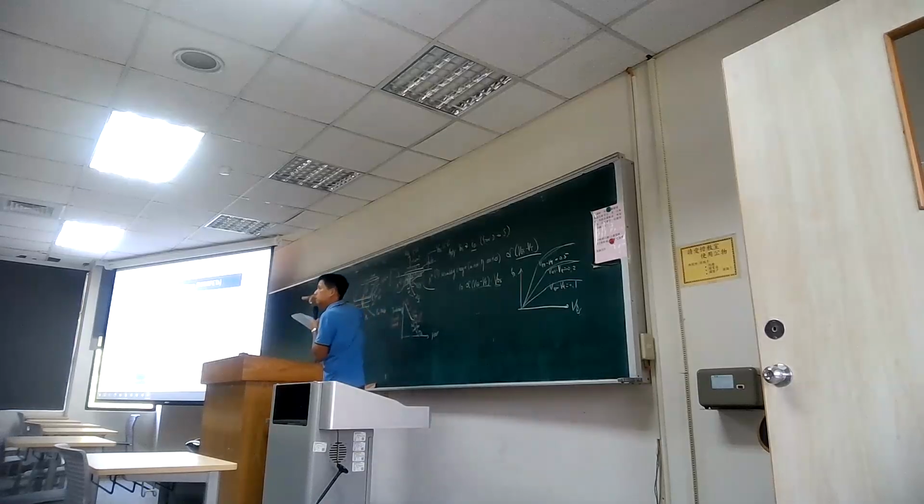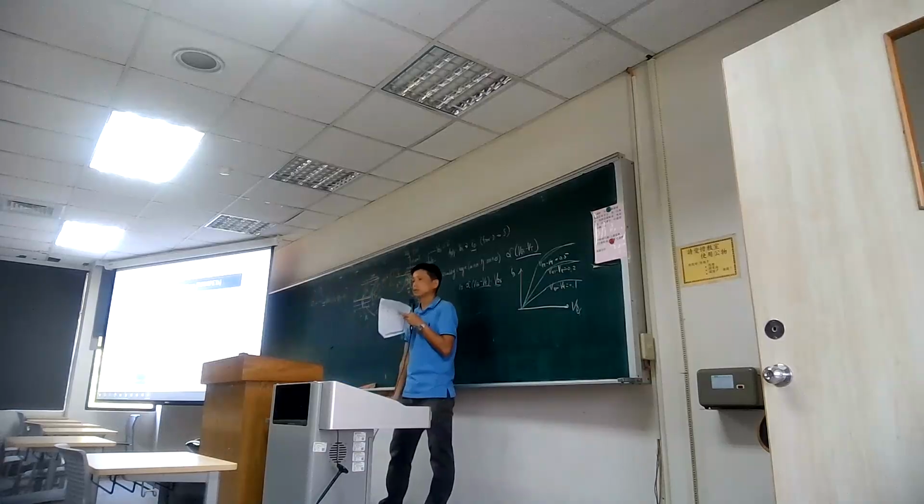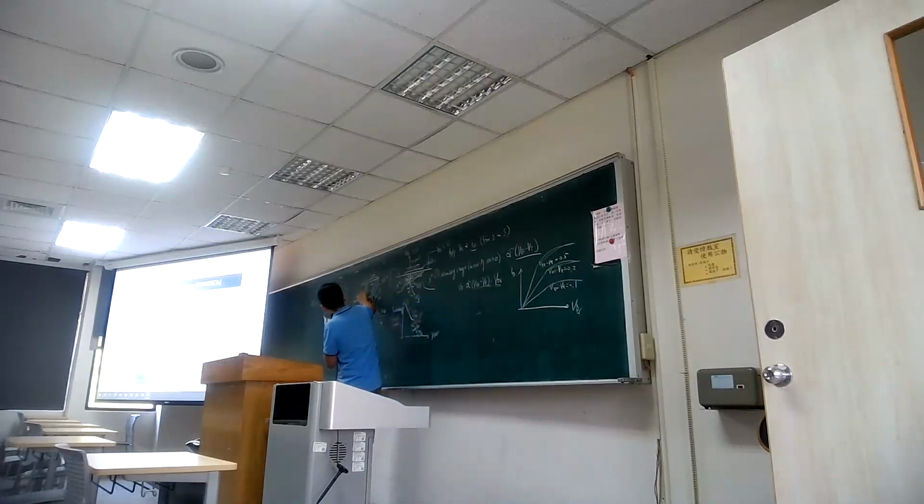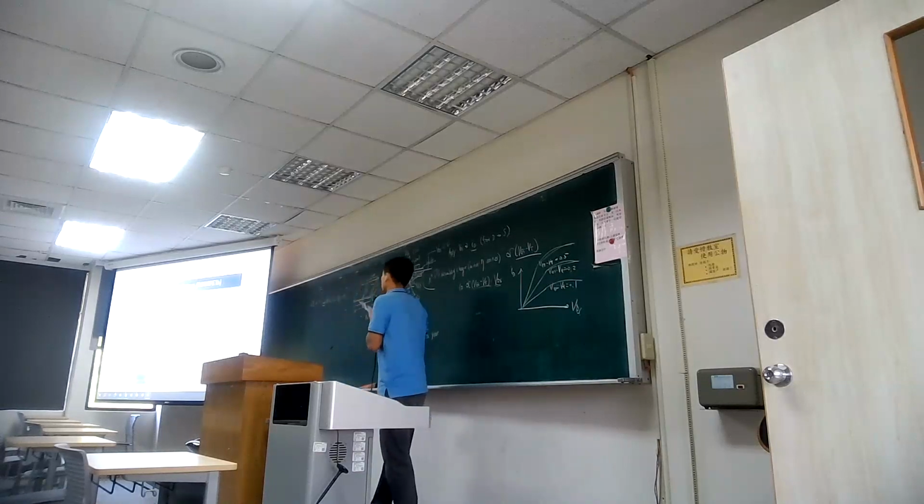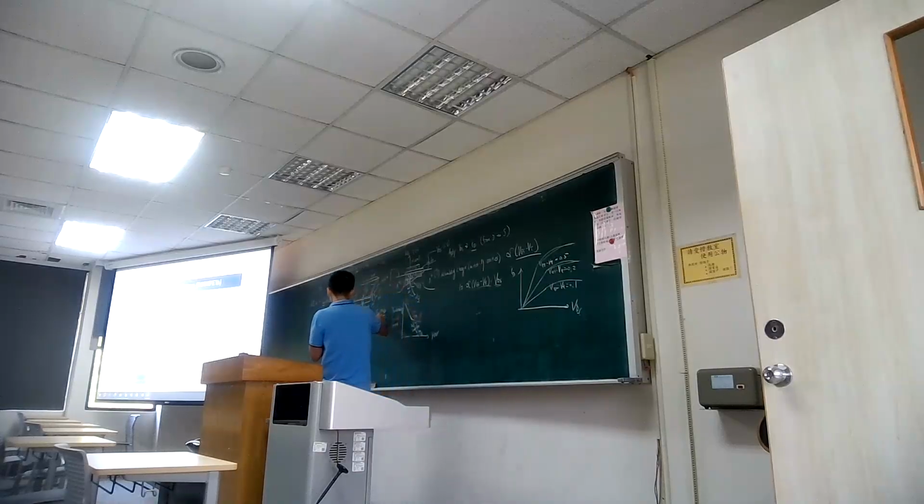And what is the distance between the two plates of the capacitance? It is T oxide. So you can write this area or the unit capacitance this way. What is the area of the charge separation? And what is the distance between these two charge separations? We get epsilon oxide W dx over T oxide. And typically, you can say it is like a strip capacitance.